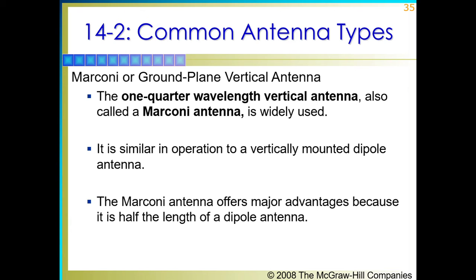This contrasts with a dipole antenna, which consists of two identical rod conductors, with the signal from the transmitter applied between the two halves of the antenna. The monopole is a resonant antenna. The rod functions as an open resonator for radio waves, oscillating with standing waves of voltage and current along its length. Therefore, the length of the antenna is determined by the wavelength of the radio waves it is used with. The most common or fundamental form is the quarter wave monopole, in which the antenna is approximately one-fourth of the wavelength of the radio waves.